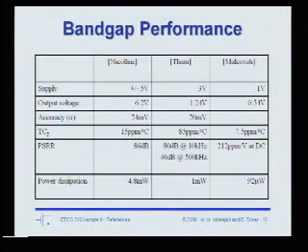So that was a very quick overview of how band gaps work. Again, I encourage you guys to read Gray and Meyer. A lot more details on this, and if you ever do design a band gap, of course you'll become an expert on this. Most companies, if you go work in a company, there's 1 or 2 people who are kind of the reference experts, and so they design all the band gaps and they know all the process corners and all the variations. And so unless you are that person, you probably will rely on someone else to design the band gap for you. But definitely it's good to have the background knowledge in designing band gaps.